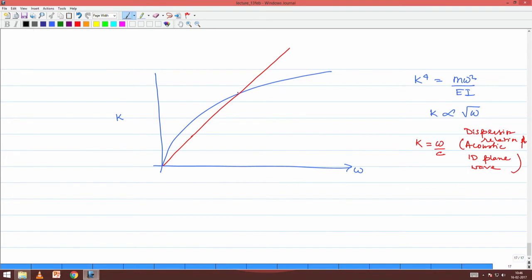Now, this crossover point is very interesting, and this frequency is called the coincidence frequency. And it turns out, and we will do that derivation in the next class, that sound radiation actually happens only for these frequencies, whereas at these frequencies sound radiation is almost negligible. The actual sound radiation happens only for these frequencies. We will come to why probably in the next class, but just before we end this class, a short story to motivate the idea that we are coming to.